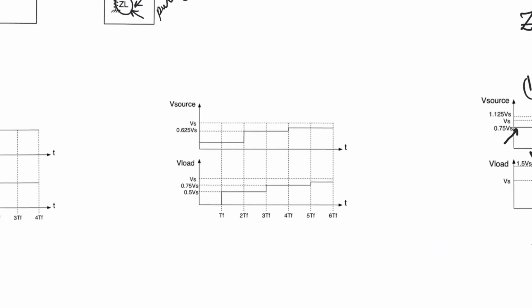Now, this is another case where we have Z source higher than Z naught. In this specific case, it's equal to 3 Z naught. And obviously, ZL is equal to infinity. That's always the case. So in this case, the source is going to inject some of its V source into the impedance of the transmission line at time equals 0. And so V of 0 here is going to be Vs multiplied by Z naught, which is the impedance of the line. And again, we have a voltage divider, which gives you 0.25 Vs. So you see a very small component being injected into the transmission line.